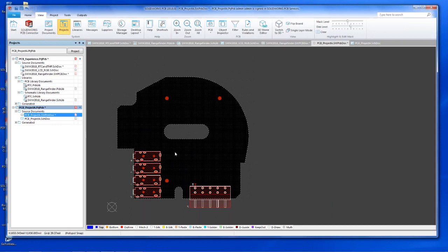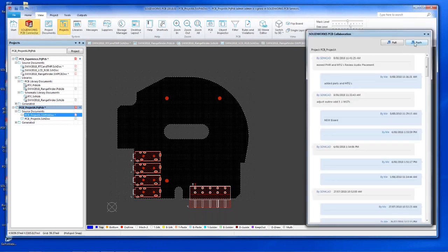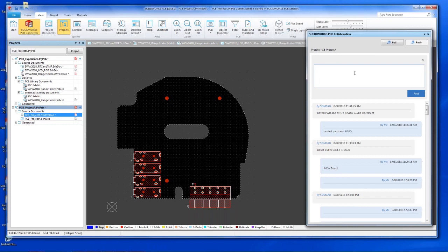I would go ahead and finish my board, do all the routing, do all the documentation, and then always, as the final iteration, I would collaborate this to SolidWorks to get that final assembly. That can also allow you to release your mechanical assemblies, including your electronic assemblies, with bills of materials, with documentation, side views, front views. All that is capable inside of SolidWorks now that you're sending real data. So we'll push this back and we'll just say that we've got this as the final PCB.